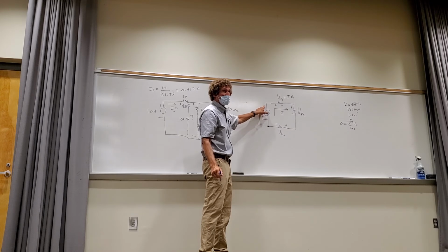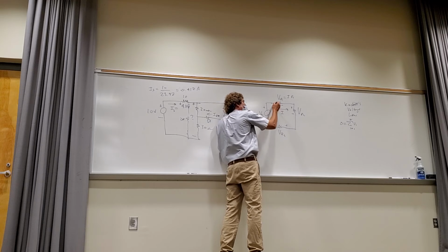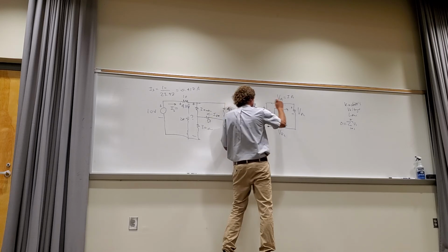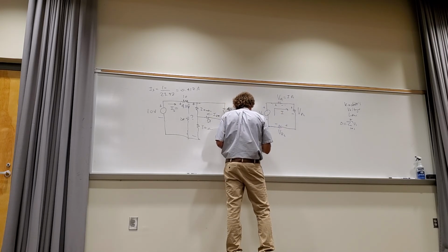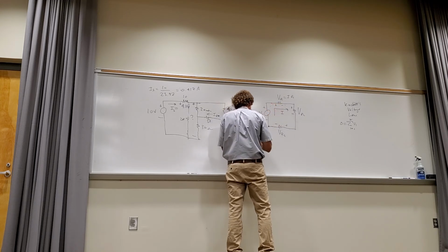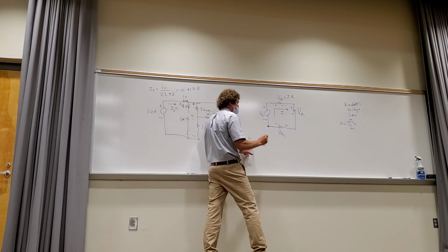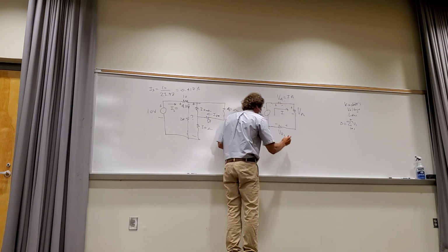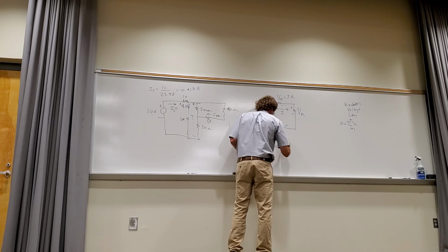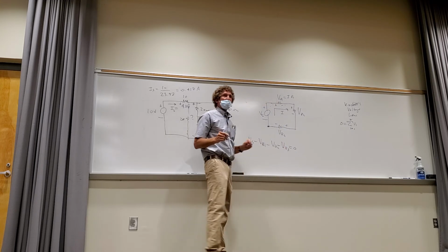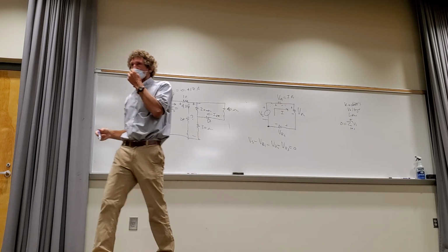Likewise, when I go from a positive to a negative, it's a voltage reduction or loss. Do y'all follow me? So around this circuit, the equation would be Vs, if I started here, an increase. Then it would be a decrease right there, a decrease right there, and a decrease right here. That's the sum of the voltages around the closed loop is 0. Y'all follow?